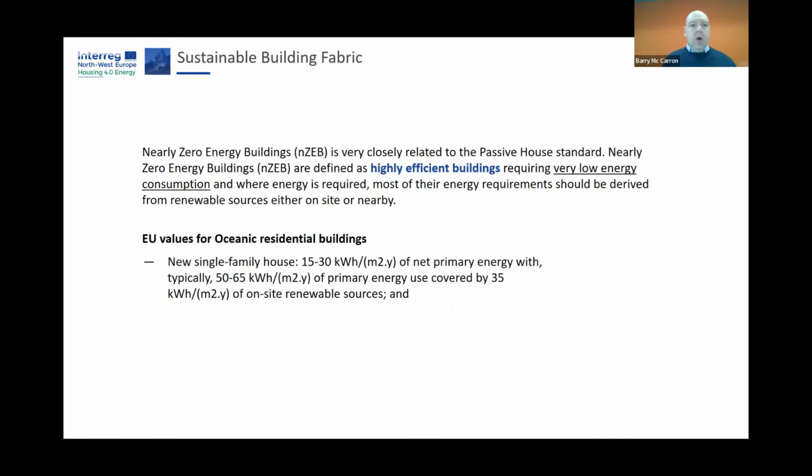So again, when we're looking at NZEB, it's very closely related to the Passive House standard. In many ways, the building blocks of NZEB, as it was designed as an EU directive, actually come from downstream from the Passive House standard. The Passive House standard has the metric of 15 kilowatt hours per meter squared of floor area in any building. What it does not include, the secret's in the wording of it, I hope that's not too patronizing, is the heating demand for hot water.